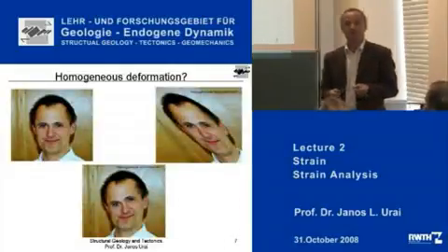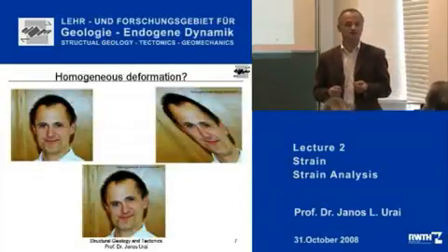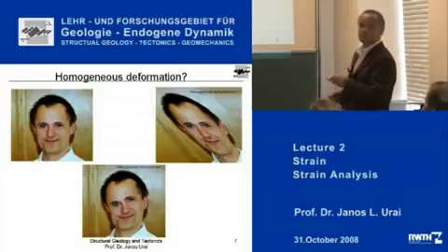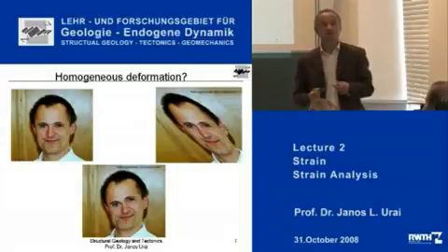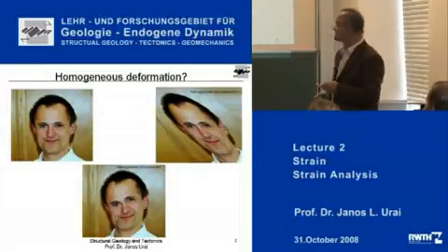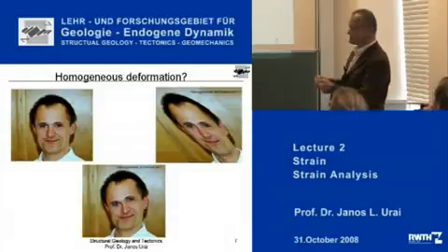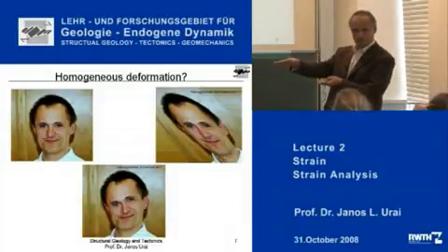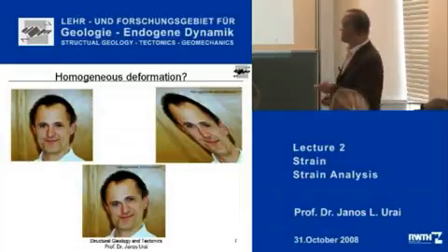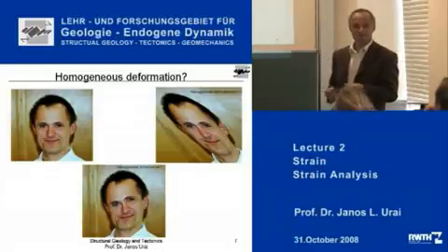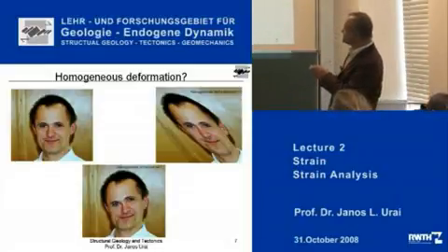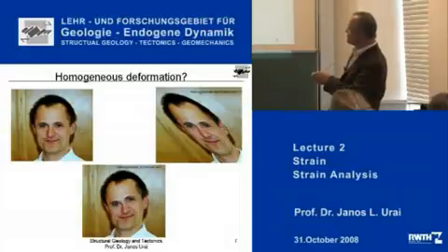Okay, here's the next question. Is this homogeneous deformation? This is the original, 12 years ago. There's more hair. Is this a homogeneous deformation? You all are nodding yes. What I did here is I sheared the picture using Photoshop, and the deformation is homogeneous. Is this a homogeneous deformation? I don't think so, because, for example, the straight line that I would be able to draw from the top of my hair down to here has now become curved.